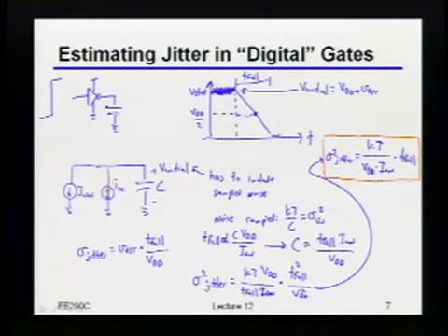We'll do in a second how you'd figure out the impact of the noise current. But basically, if you wanted to figure out what that is, it's fairly straightforward. The timing error is just equal to whatever the voltage error was, normalized by the edge rate of my transition. What I mean by edge rate here is that if I have a certain voltage error, I should normalize it by my overall power supply, because that's the total voltage swing I need to do, and then multiply it by how much time it takes me to go from VDD to ground in the first place.